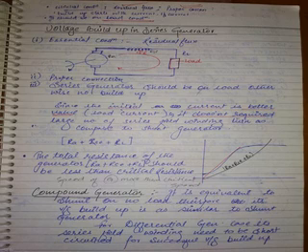So now you can't say IF is the basis, it is IA. So when there is no current, for example, what will be the voltage? 6 to 8 volts. So slowly as IA develops, automatically what happens? The voltage will rise and it becomes saturated. As you keep on loading the machine, up to a field current value only the flux will increase. But after that the flux becomes constant, and the same thing you will observe here.